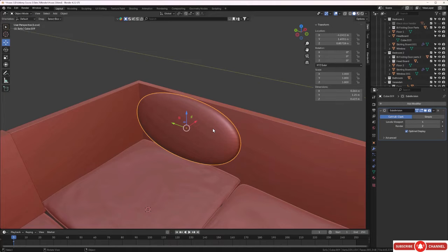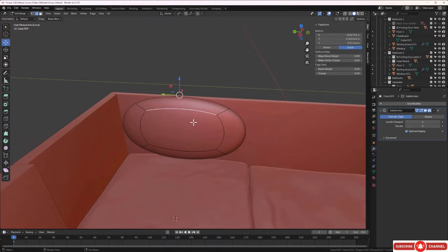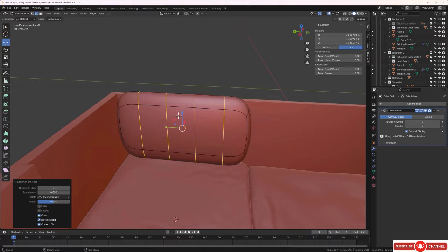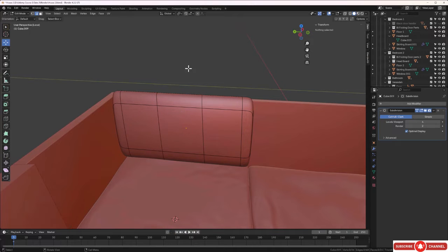So let's tap into edit mode with this one, and let's select this edge here, and we'll press Ctrl R, and we'll put in 4 loops, and click again. And now before you deselect, let's scale those up in the Y, so S and Y, and just pull those out closer to the edge to, I'd say, something like that.